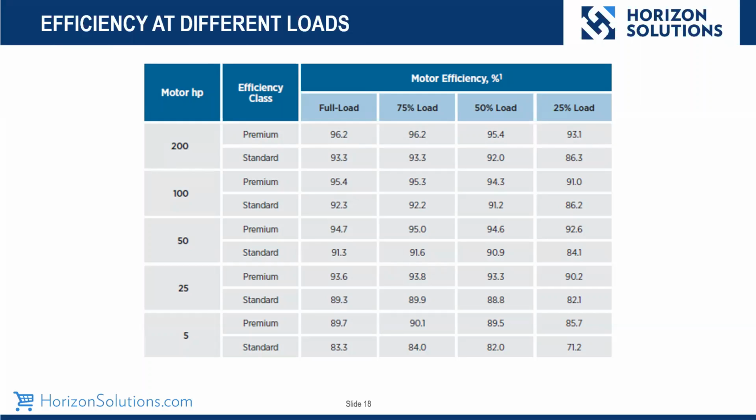The approach that a premium efficient motor is less robust than a standard motor is not true. They are as robust, if not better, especially when you have the MG1 rating, because they have to meet that. So over the years, from when it began in 1987 and all the way through, you can see that the technology of the drives especially has increased, and the build of these motors has definitely become more robust with the MG1. Next slide.